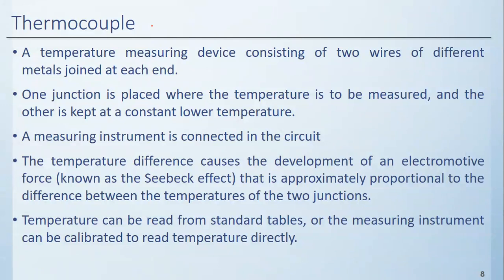Now, when the thermocouple comes in contact with the hot body, and the other end has a cold body, an EMF is produced in it, according to the Seebeck effect. This EMF produced is approximately proportional to the change in temperature. If you can measure the EMF produced, then you can relate it to the temperature change. The temperature at one end is known, and the other end you can calculate.